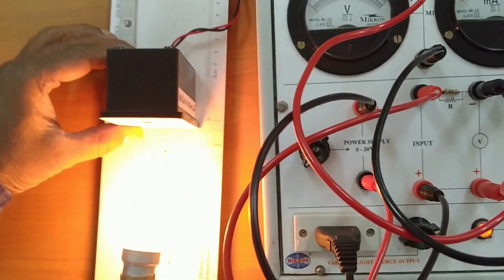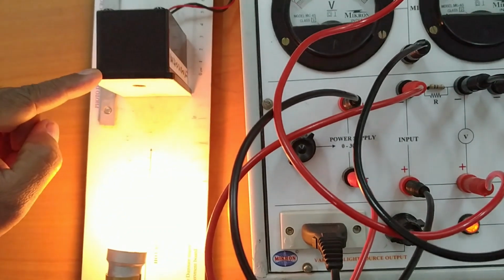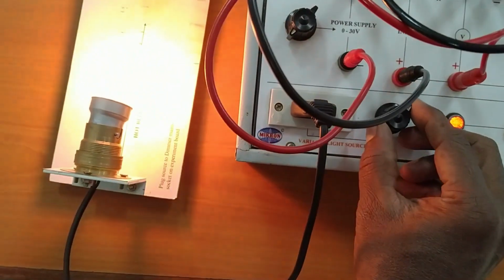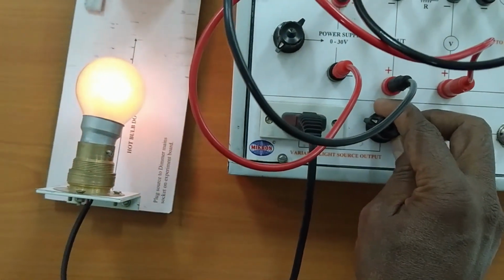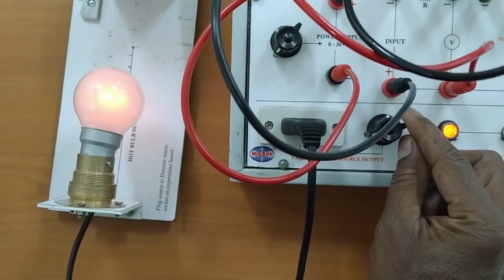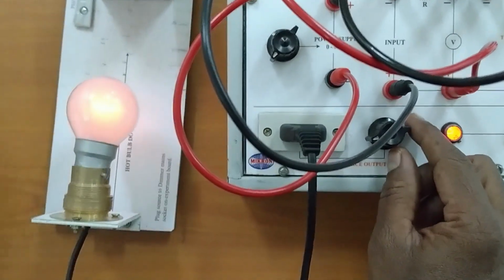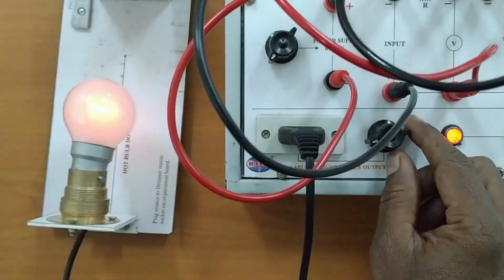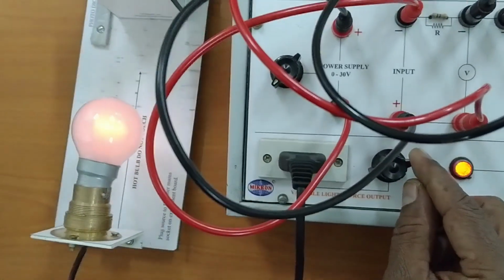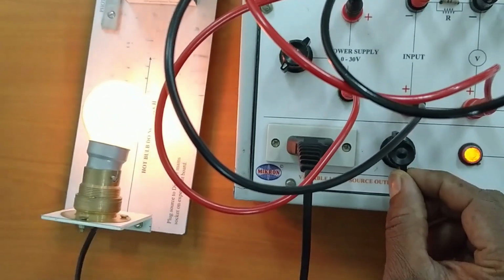Instead of changing the distance between the lamp and the photodiode, I can also alter this. This is the knob, and I can make the intensity less. This is the lower intensity I can make by turning this. Okay, so almost zero. This is just like your fan regulator. In the house you use fan regulators, and you can keep it at 1, 2 or 4 to increase the speed. But here it is a potentiometer where I am changing the resistance, thereby the current changes and the intensity of the light emission also increases.